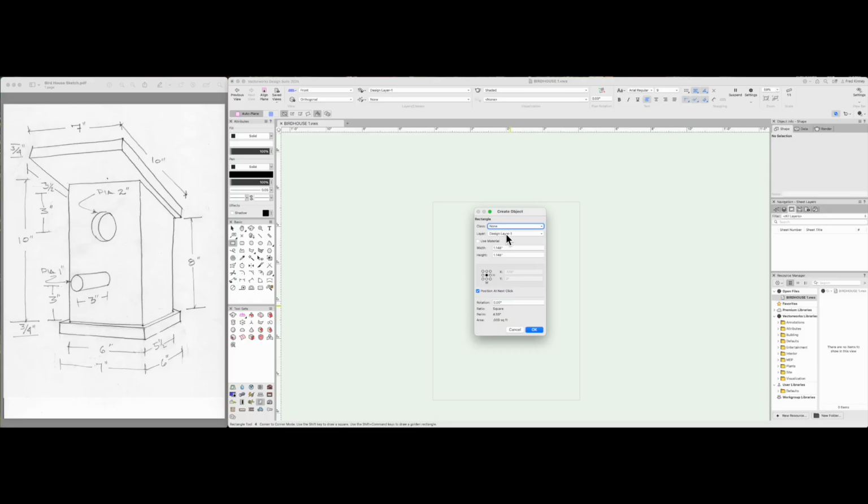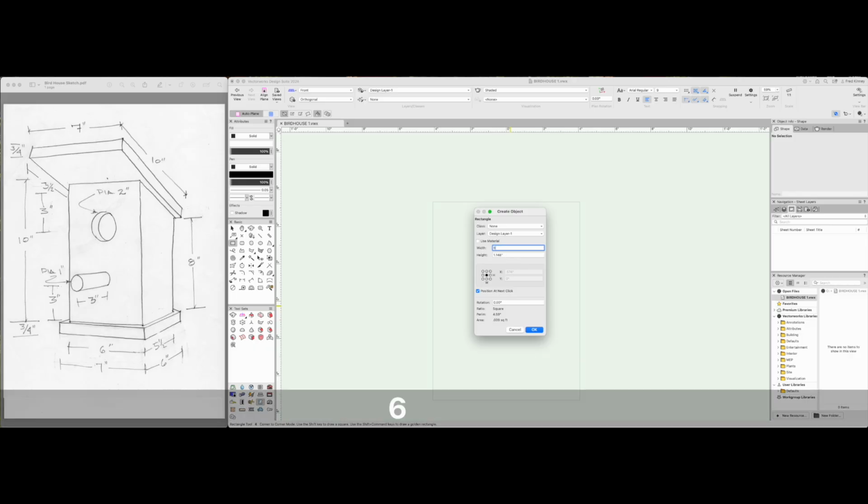For this project, we won't worry about those aspects yet. In this case, it does show the width and the height. So the width of our thing is 6 inches, as you can see called out by this dimension. In Vectorworks, the way it's set up by default is inches are our primary measurement, so we do not need to state what that is.